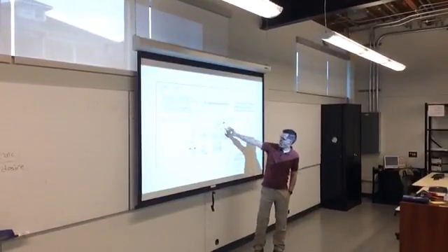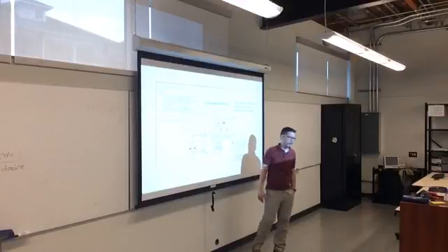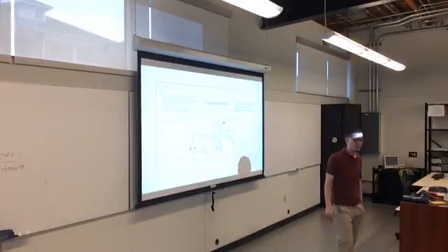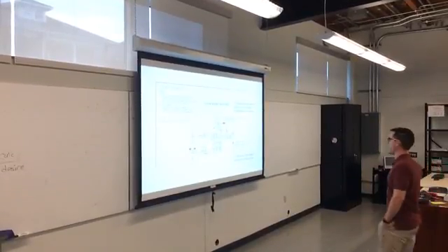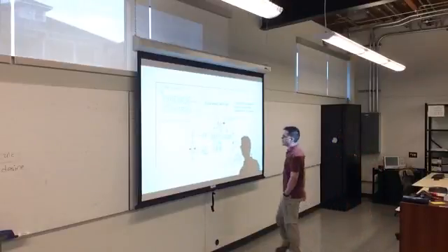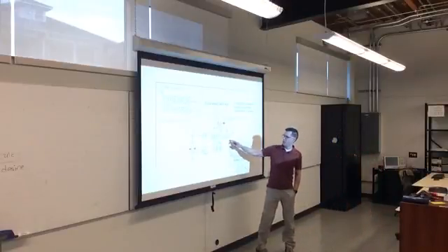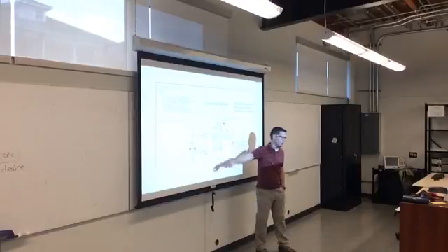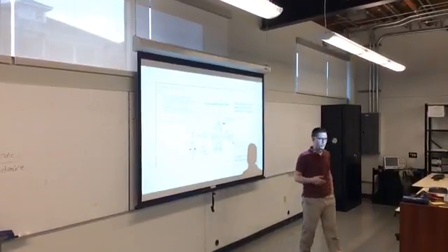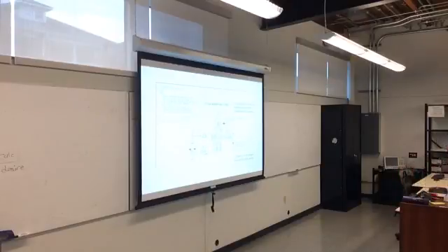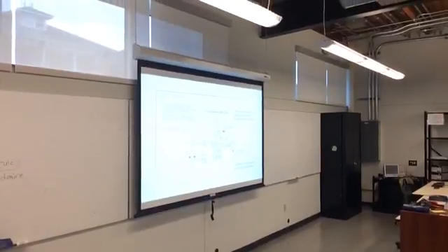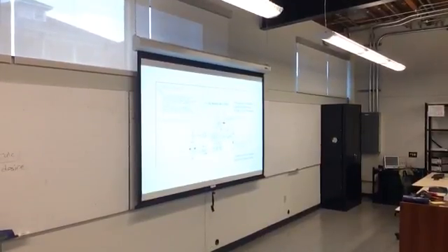The final thing is that depending on how this SDO line, which is serial data out, which we don't use, is configured, you can change the address of the accelerometer. You can change the lower bit of the address. And they have already tied it to high, so you know what the address is. I'll leave this slide in the documentation for you to figure out what the actual address is.